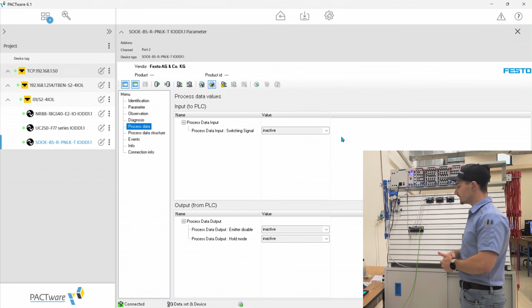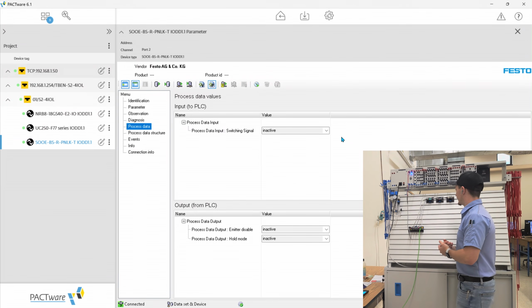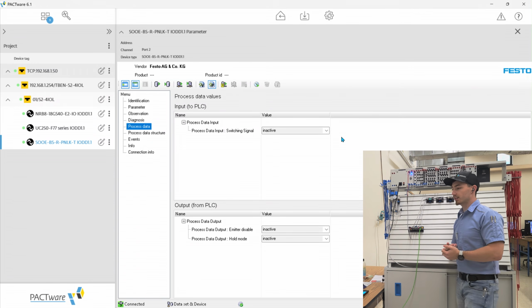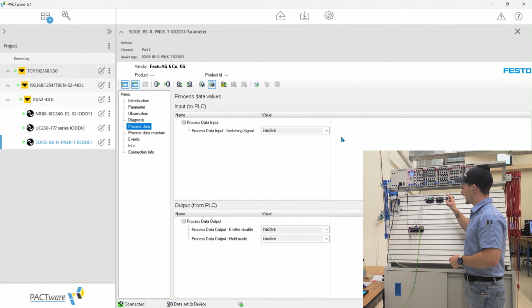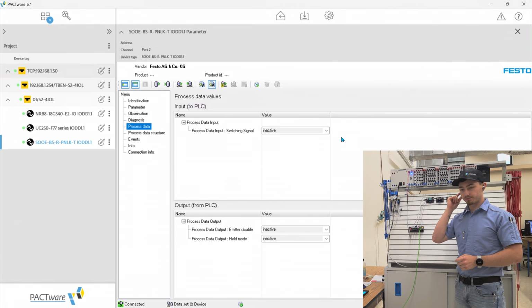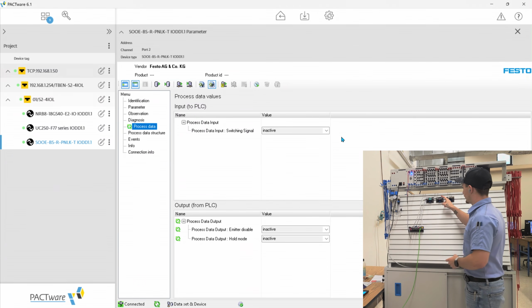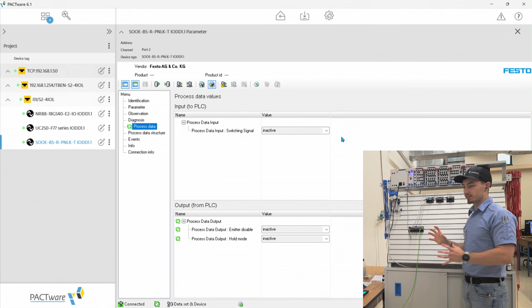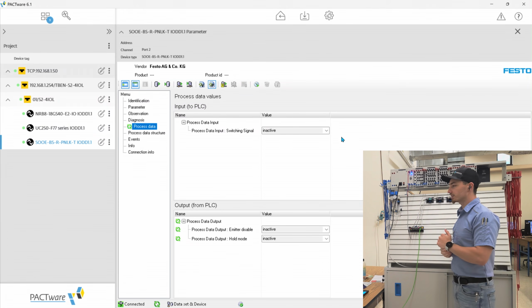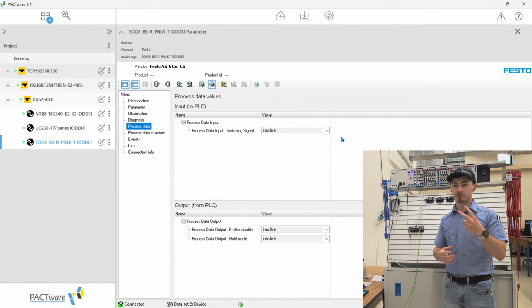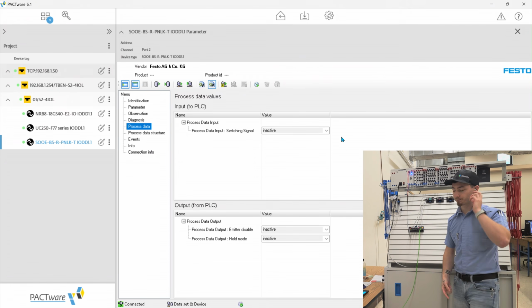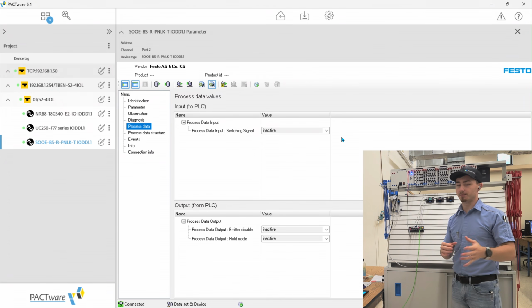Okay. There's also different types of this light sensor. There is a through beam, which actually has two sensors, and there's one that is sending and another that is receiving. That's the most reliable type of sensor, but they are more costly because you're building and paying for materials for two sensors instead of just one. So that's called through beam.